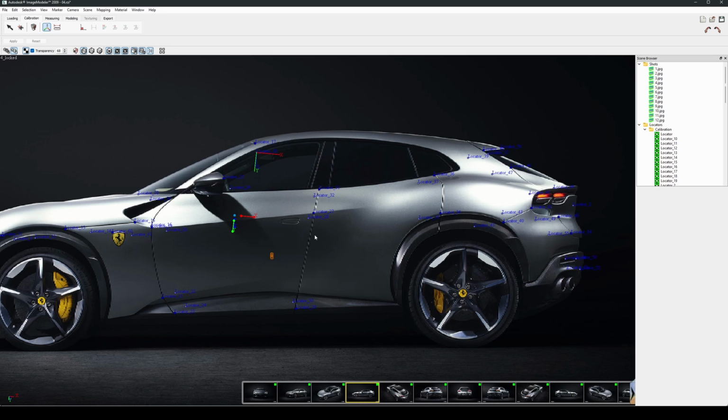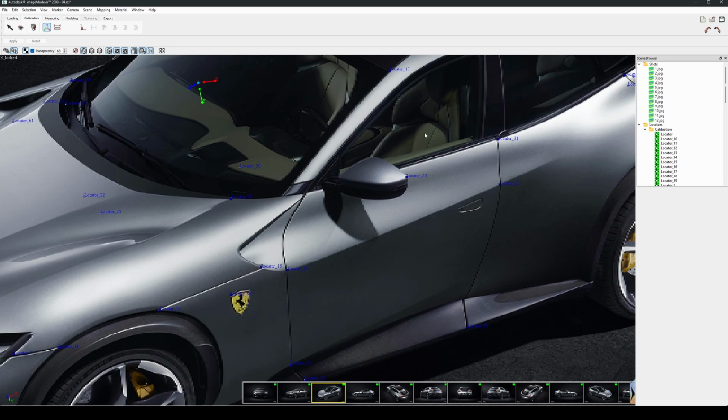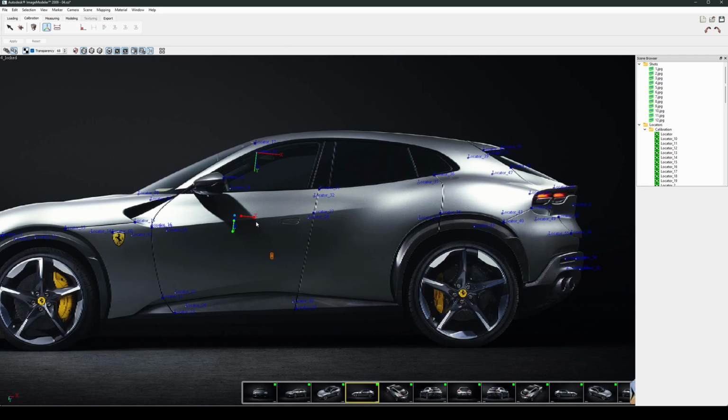So basically we want to tell the program that from here to down is the z-axis, and then from here to this side is the y-axis, and basically from here to about this side is the x-axis. Now to do this, let's get back here. We're going to take this, I'm going to left click and drag. Now basically this is going to be snapping to a locator. It's not going to be snapping to anything else besides the locator.